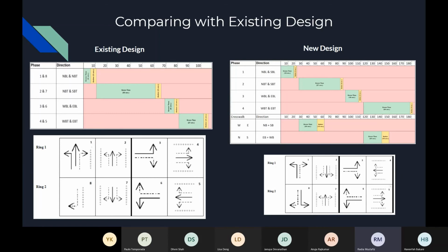The green time intervals for northbound/southbound through and eastbound/westbound through traffic are more similar in length for the tentative design. In general, the green times are longer and the intergreen periods are smaller in the new design compared to the existing design. The amber intervals are shorter in the tentative plan as well.